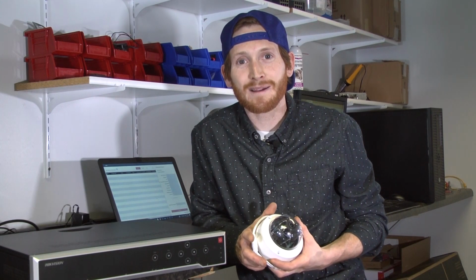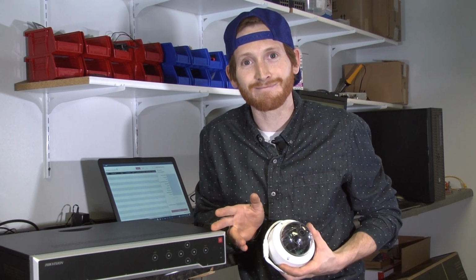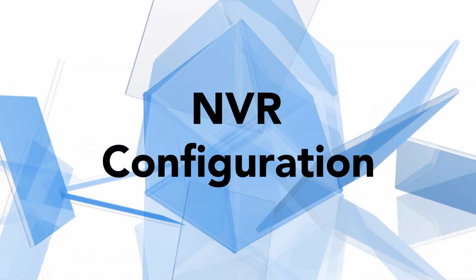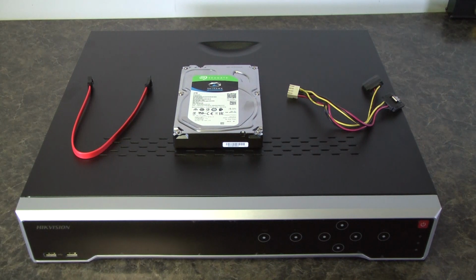Now that our IP camera has been initialized, we're ready to set up and configure our NVR system. The first step for setting up and configuring our NVR will be installing the hard drive. We'll gain access by removing 2 screws from the back of the NVR and install the hard drive.